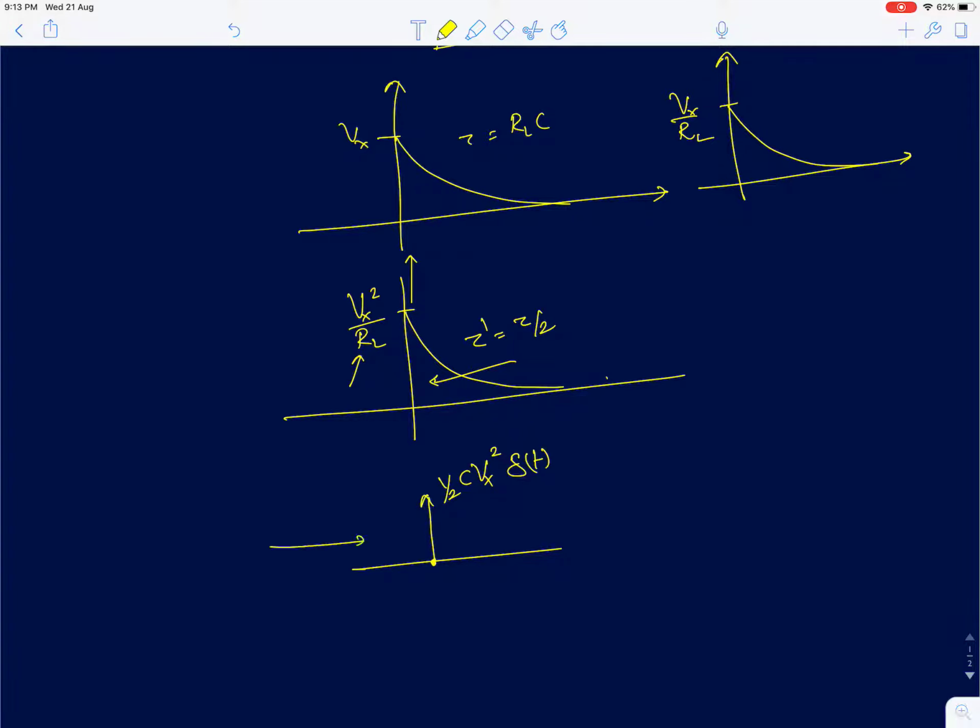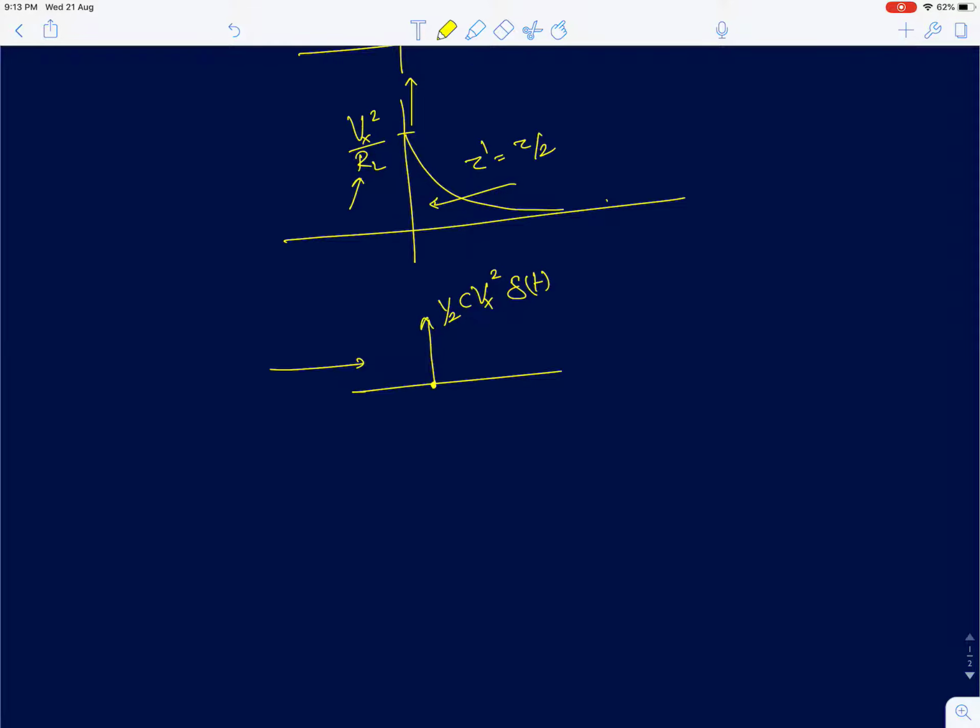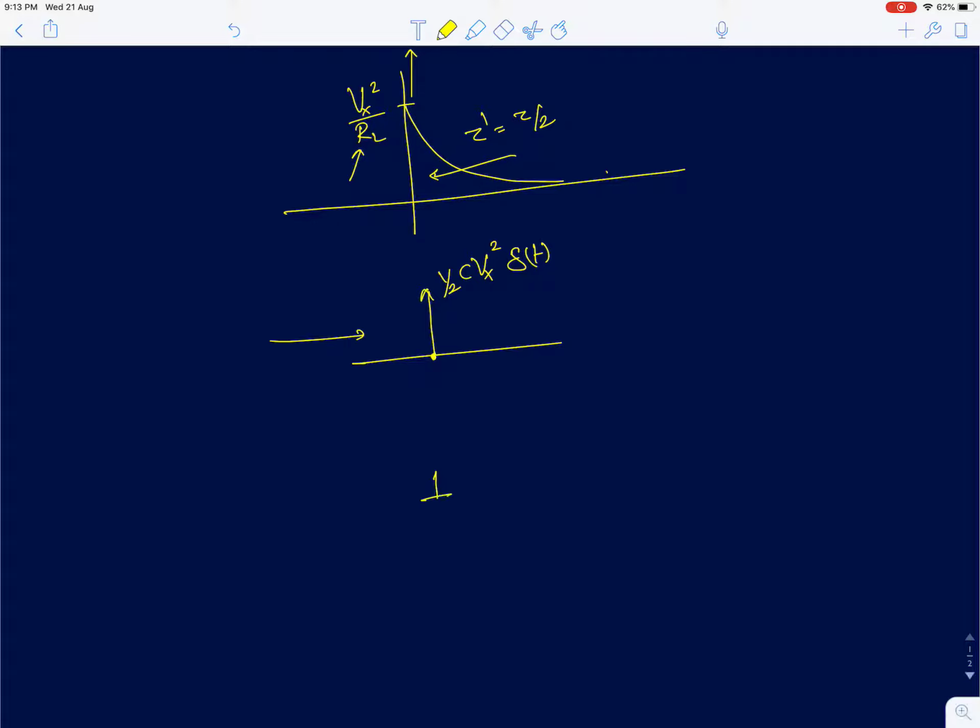Now this is an ideal capacitor, meaning it can actually deliver infinite power if the load demands it. But any practical capacitor cannot deliver infinite power. And as we discussed in the previous lectures, to capture the effect of finite power, we normally model a series resistance Rs. I'm going to call the capacitor Cs to say that they are in series: a capacitor of value Cs with a series resistance Rs. By connecting Rs, I'm capturing the finite power nature of the capacitor.